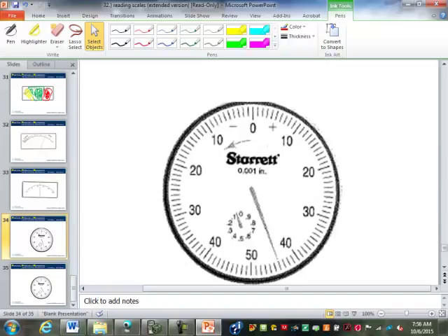And see, I use the digital, but the problem with digital is you need batteries in them, and they run out of batteries fast. If the batteries get low, they don't necessarily stop working. They just start giving you funny readings. The old analog meters, they still took batteries or they plugged in, but they either worked or they didn't. They didn't give you funny readings when the batteries got low.